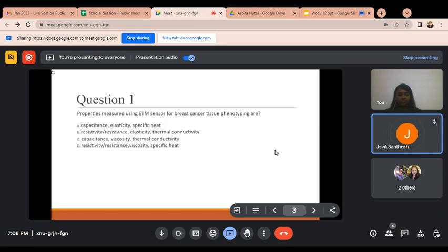No, ma'am. Okay, so piranha is a wafer cleaning process where we mix H2SO4 and H2O2 in the ratio of 3:1, and this solution mixture is used to clean the wafer.